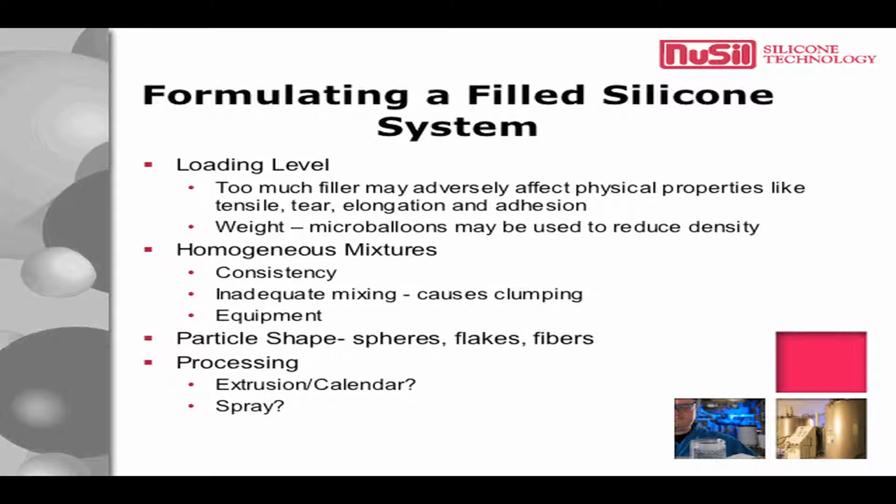What type of equipment is used to put these in? Things with a lot of shear, a lot of power, slow speed. Now, particle shape, and I mentioned before different things like spheres, rods, cones, different things like that. You have to be very careful when you're mixing these in. If I purchase a bag of a specific filler to add into a silicone elastomer and it's a cone, and I choose a mixer and a time and a mechanism to mix this that breaks those cones, it defeated the purpose of using that type of filler for the conductivity you're looking for.